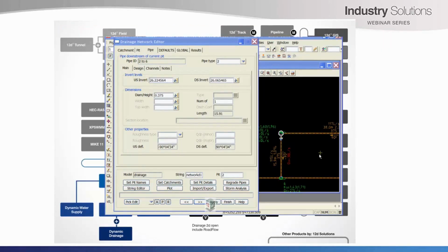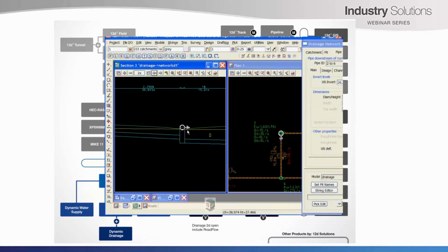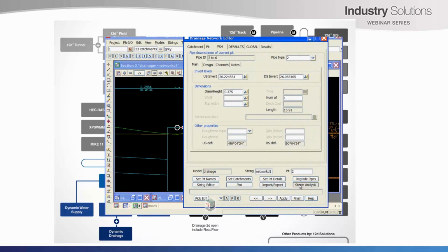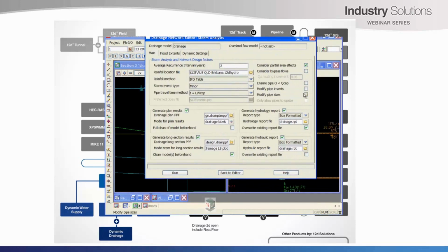The 12D model drainage analysis module allows for the hydrological and hydraulic analysis of a drainage network. Site-specific rainfall data can be entered and stored in a rainfall file that can be utilised across many projects. Using the rational method, catchments with variable runoff characteristics can be created and maintained, with the time of concentration calculated by typed input or automatically determined by graphical flow path creation.